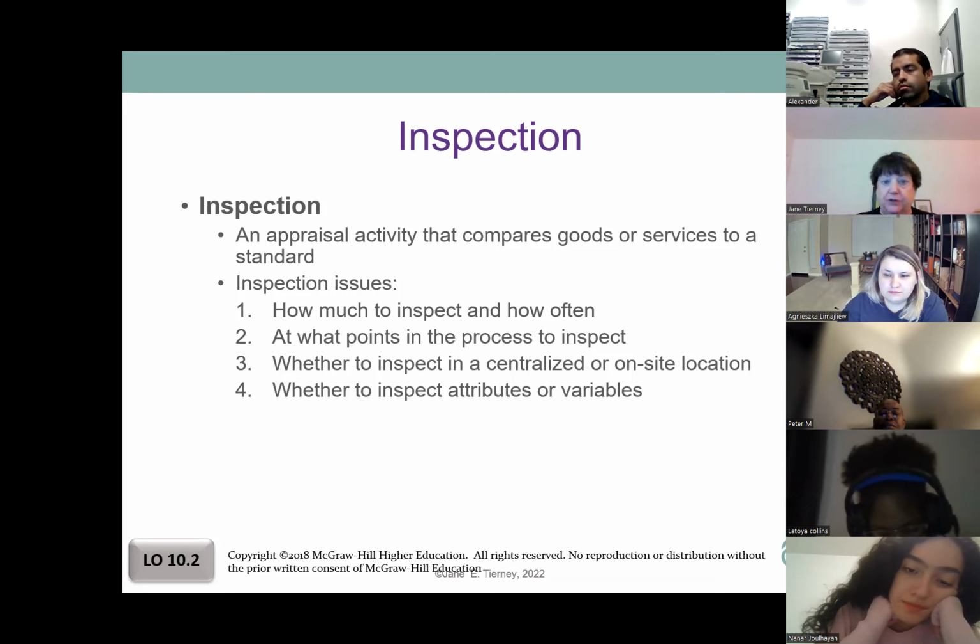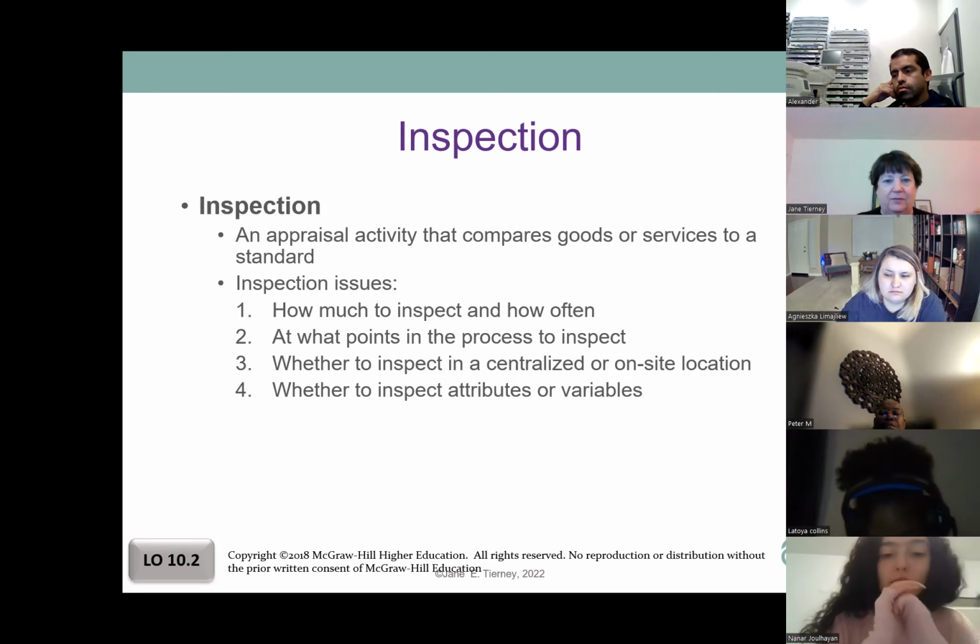And if you have plumbing too, for sure, because you want the plumbing in the right position relating to the wires, because both go through those walls. You don't want pipes to sweat and drip down onto electric wires, because that's a recipe for disaster, right? Water and electricity don't go together well. So you want to keep them apart.